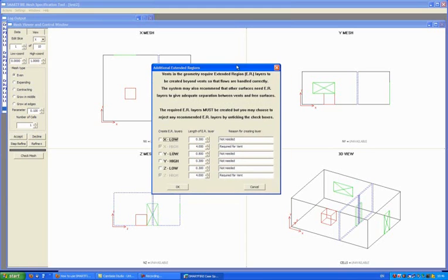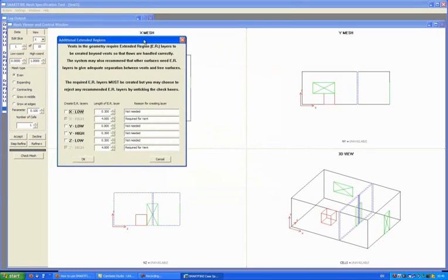The meshing system now moves on to considering extended regions, and extended regions are required outside of vents. So we define the geometry inside the region boundaries. Any vents require extended regions outside in order to allow the flows through those vents to be computed accurately.